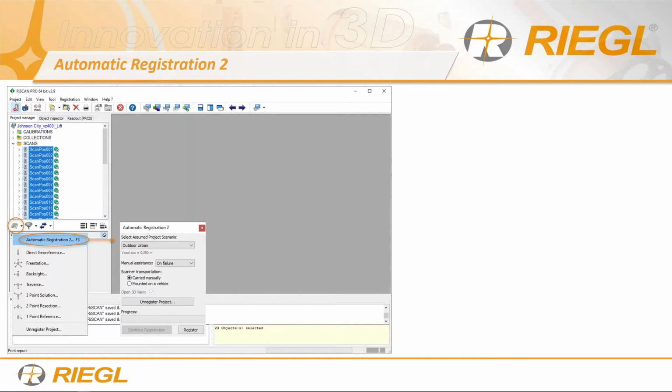On a tripod, there's no metal around it, but on a vehicle, it assumes that it's metal, so the projected error on the digital compass is much higher, and it accommodates that based on the selection right here. So select the appropriate platform that you're using, whether it's a tripod or a mounted vehicle.